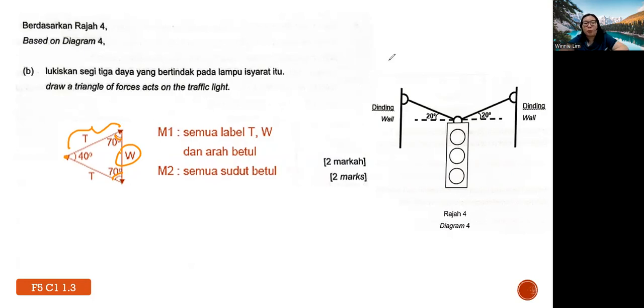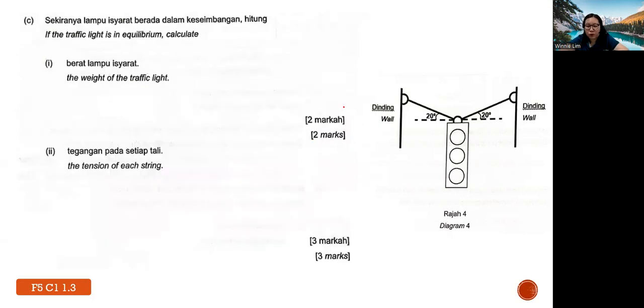But if you prefer not to draw, or you do not have a protractor, then you can choose to do calculation. For calculation, I will use the resolution method because you also learned resolution of forces in 1.2, right? How you solve it is basically this force with an angle. You can resolve it into two components. We call them what components? X component and Y component, Fx, Fy.